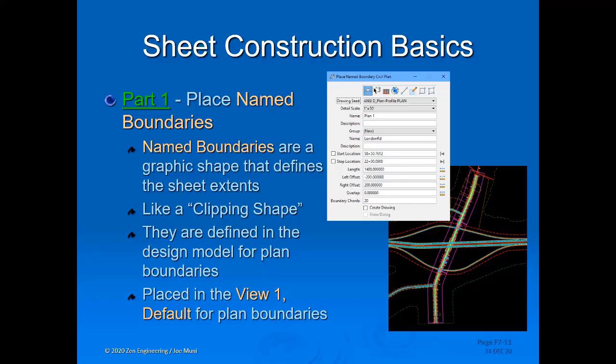Now, I don't know exactly how you guys have been creating sheets in the past or over the years, but I know when I was in the production world, the way my agencies and companies worked is we just worked directly in that design model space. And again, there were slight flavor changes of how it was done from company to company, but essentially you would draw out a shape in the design model, and then you'd use that shape to clip out all of your references and then rotate your view and then reference in a sheet border. Okay, this is essentially the same process with the OpenRoads Designer tools, except it's all automatic. It's all automated using these tools.